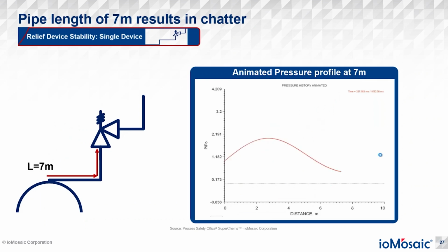When those two factors become coupled, they become greater in sync, and then they start to chatter. So what we're seeing now is a chattering of the valve, and that's not what we want at all. We can see the pressure spiking, and then a bit of under pressure. That is complete coupling, and that's instability. We obviously want to make our systems more stable.